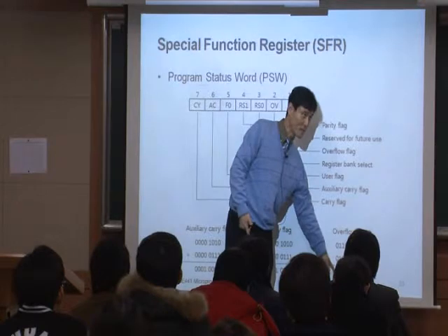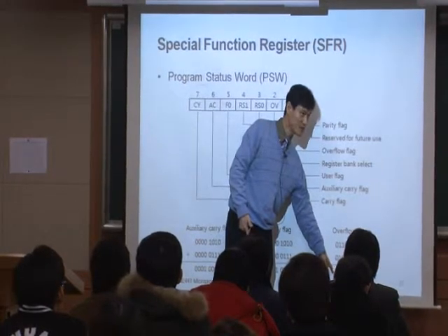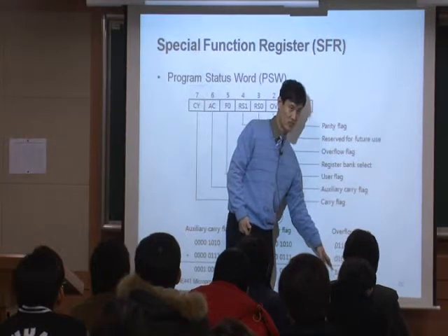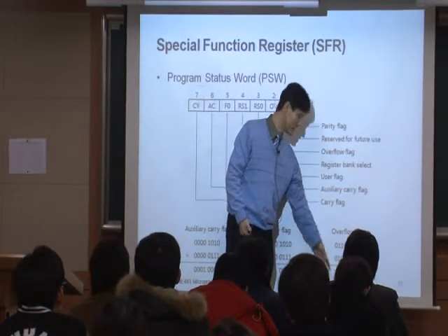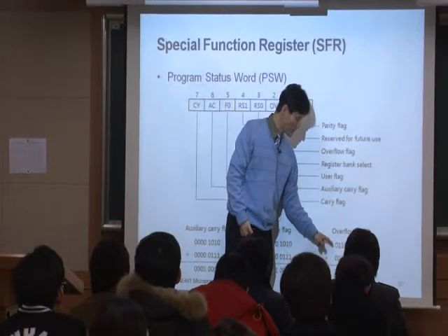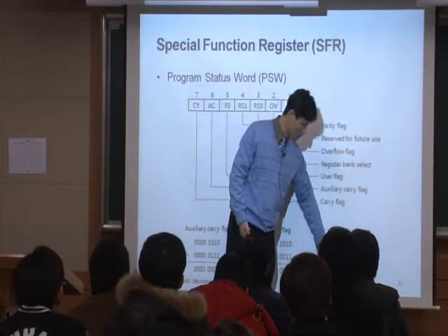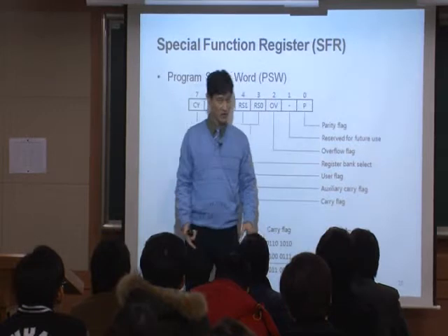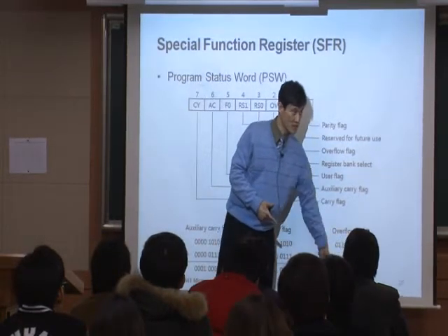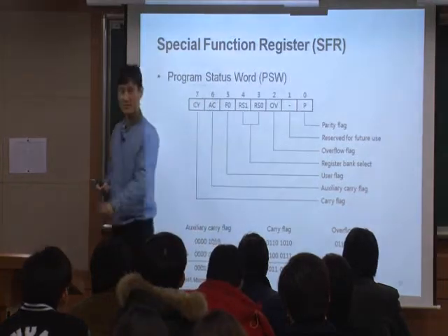Still the output is the same. Okay? You don't have to say unsigned or signed to do this binary addition. Binary addition is always like this. Doesn't matter, right? And for the microprocessor, if both of them are 0 but the output is 1, I'm talking about only the first bit. Okay? If this happens, then it's overflow.